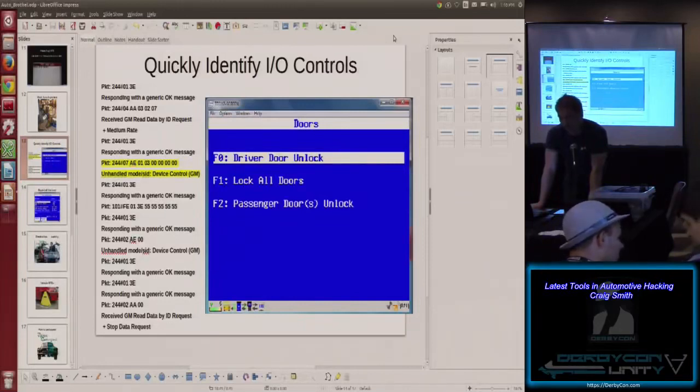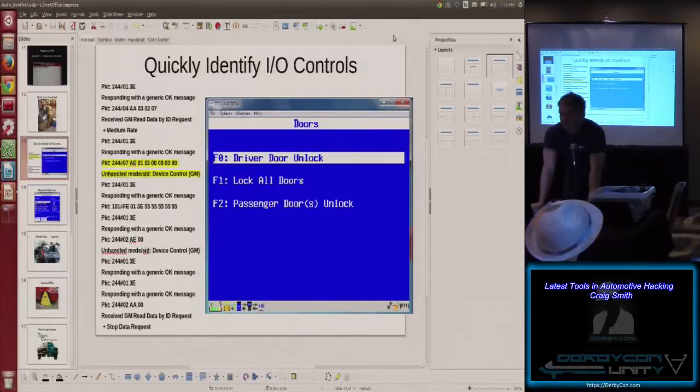If you want to hack into that one, you're going to do it differently, usually through update software. If it has a way of uploading DLLs or new firmware versions, that's a good place to start. You can also take the radio unit out and look for JTAG and serial lines into it. Some of the newer vehicles have Ethernet now, and you would just treat that like you would a desktop unit.